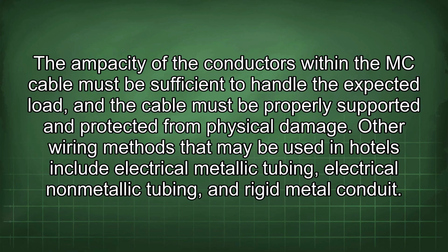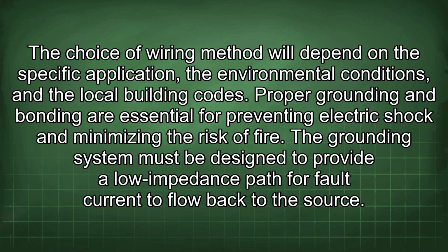Other wiring methods that may be used in hotels include electrical metallic tubing, electrical non-metallic tubing, and rigid metal conduit. The choice of wiring method will depend on the specific application, the environmental conditions, and the local building codes.